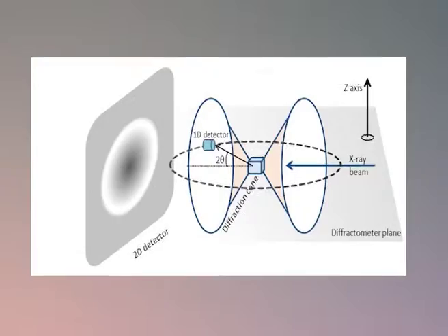The intensities of the diffracted beam in this method are recorded by a detector which is fixed on a movable carriage, which can also be rotated. The angular position is thus measured in terms of 2 theta, where theta is the angle of diffraction. Powder diffraction data are presented as a diffractogram in which the diffracted intensity is shown as a function of the scattering angle 2 theta. An instrument used for performing powder measurements is the diffractometer.